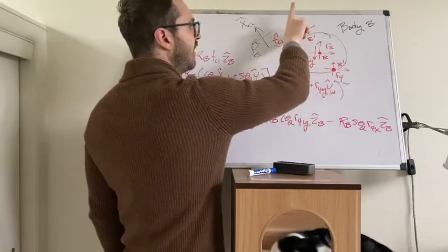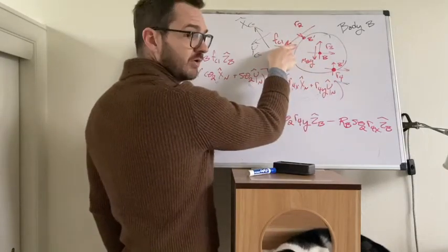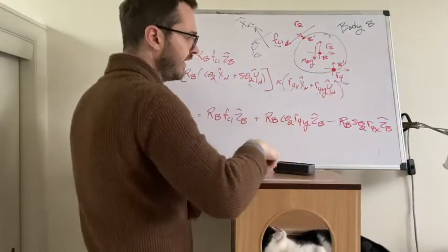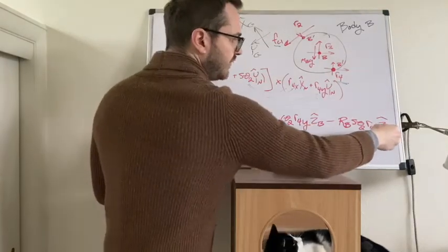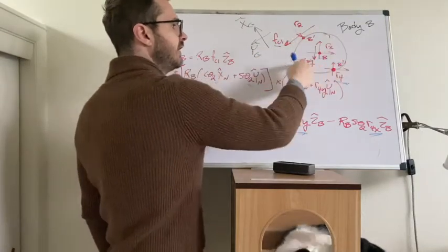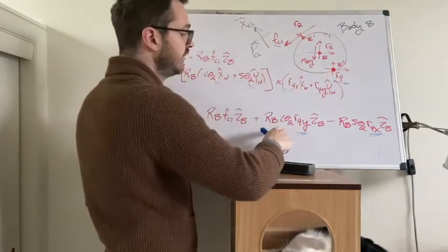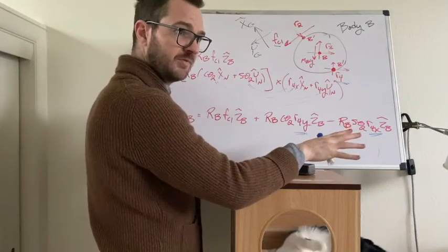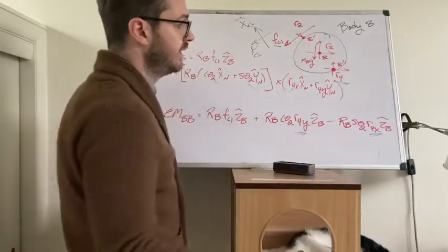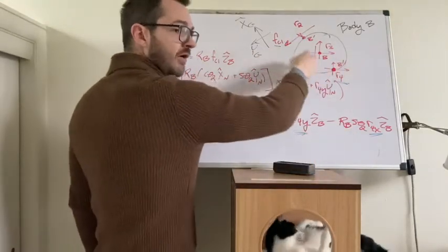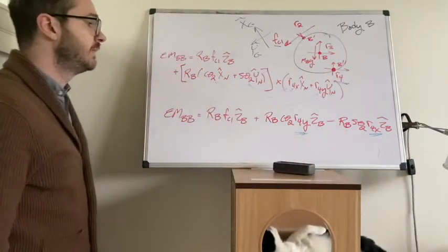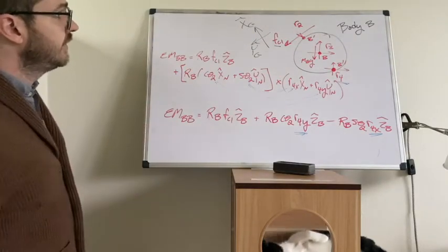And a force in the positive Y in, if the mounting location was here, that would also create a negative moment. So even if the forces themselves are positive, depending on where on the disc is the current position of the mounting location, sometimes it'll be positive, sometimes it'll be negative, and that is taken care of by these trigs. The cosine and the sine of theta 2 is specifying where on the disc the contact point is, and then of course these sometimes will go positive and negative. Okay, this looks good. So this was body B.